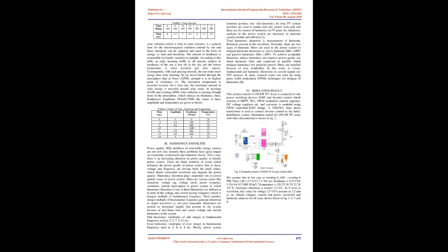Harmonics are defined in terms of voltage and current having a frequency which is an integral multiple of the fundamental frequency. These positive integer multiples of the fundamental frequency generate distortion in the output waveform, i.e. it is not purely sinusoidal. Harmonics are unwanted signals present in the system because of nonlinear loads, and they cause voltage and current harmonics in the system.